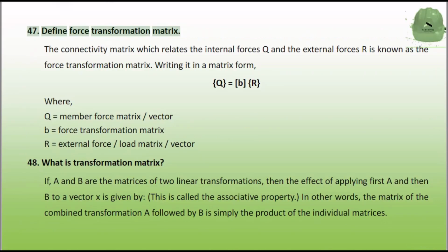Define force transformation matrix. The connectivity matrix which relates the internal forces and the external forces is known as the force transformation matrix. Writing it in a matrix form, Q equals BR, where Q equals member force matrix vector, B equals force transformation matrix, R equals external force load matrix vector.